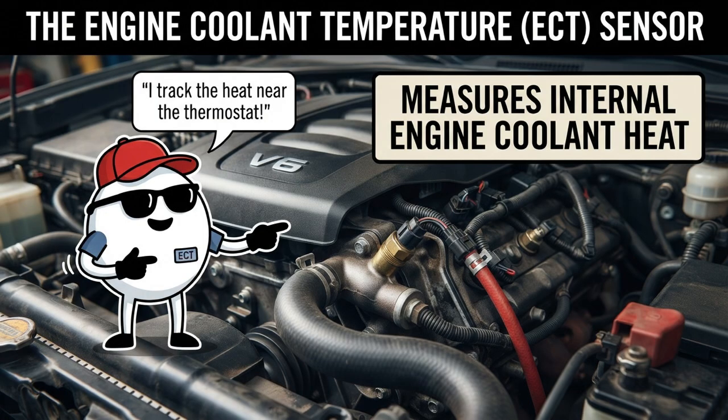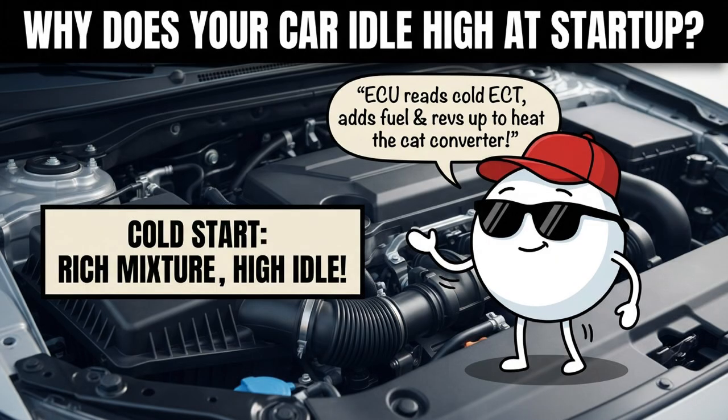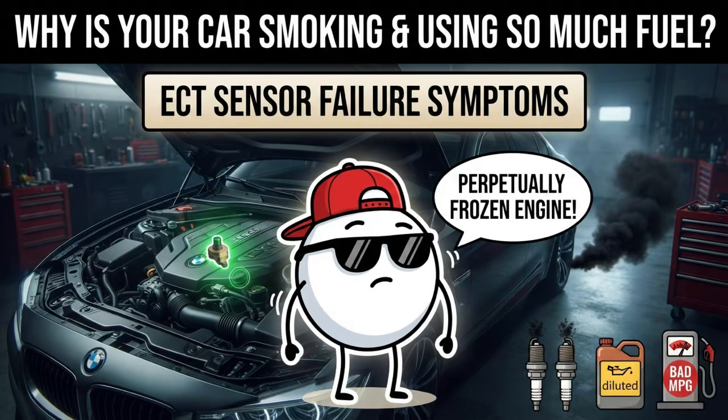The engine coolant temperature sensor, or ECT, measures internal engine coolant heat near the thermostat housing. During a cold start, the computer reads high resistance from the cold ECT and commands a rich air-fuel mixture alongside elevated idle speeds to warm up the catalytic converter. If the ECT fails cold, the computer assumes the engine is perpetually frozen.